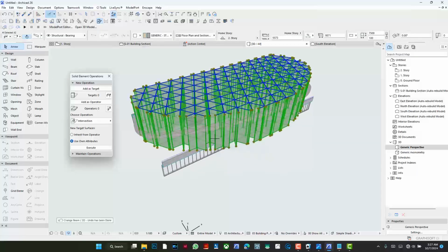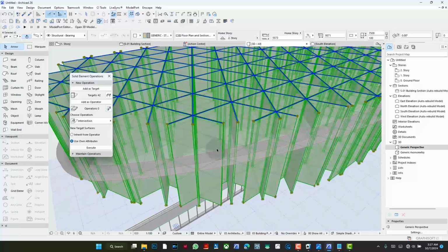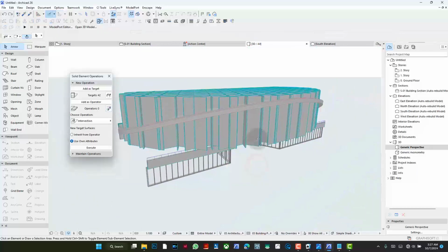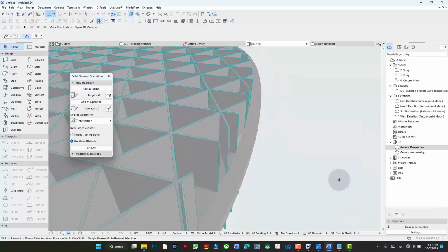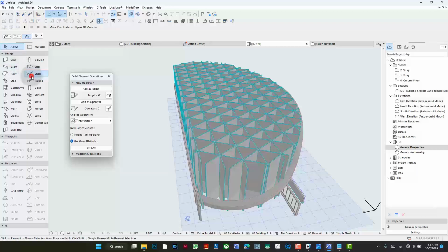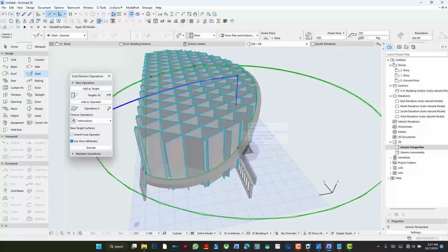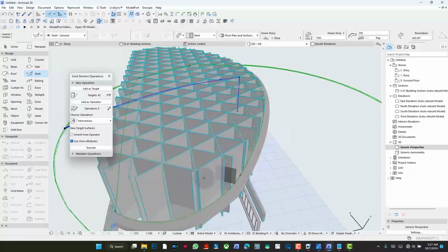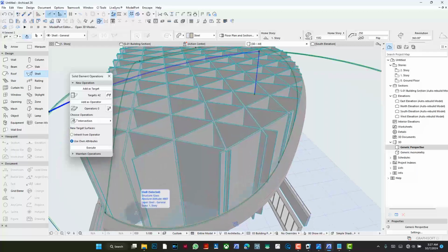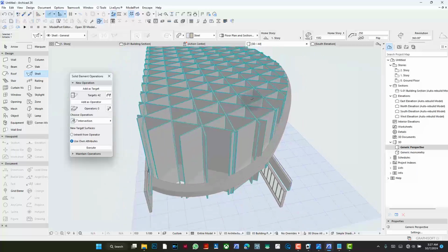One of the things I had observed in the last step was that grouping, or suspended grouping, was off. I'm going to put this back on. Set all of these as the target once again. Find a steel shell. I think our shell is missing. Okay, there's 3 of them. So release this one, and one of these 2 is steel. This is the glass one, so the steel one is the one that is selected right now, and we can see that here. It's the 250mm thick shell.